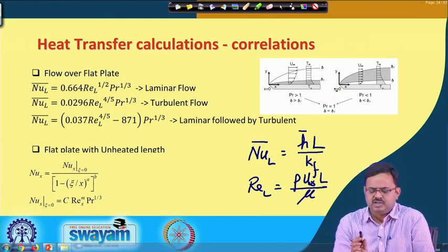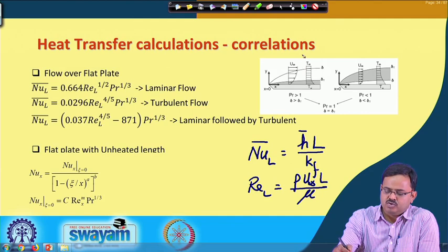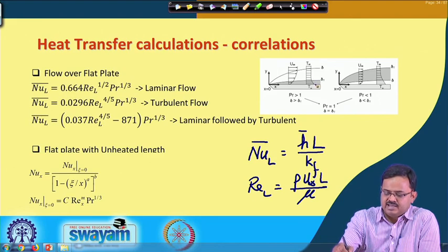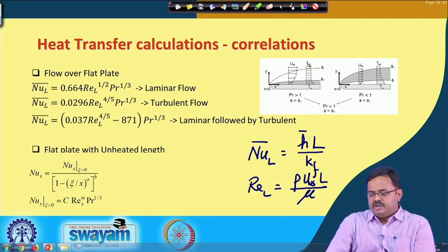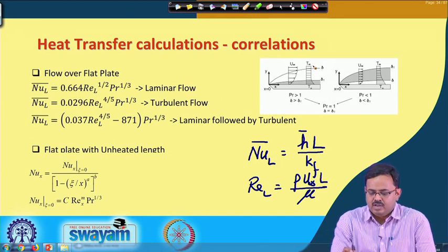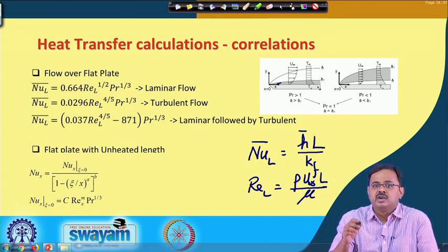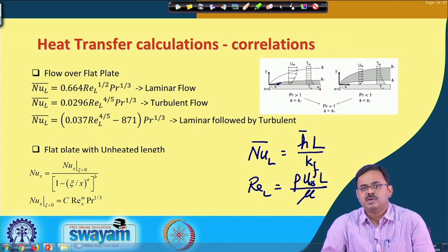So, this is flow over a flat plate. Forget all this. So, you have a fluid flowing over a flat plate, and as we know, velocity increases from 0 to the mean value as you move away from the plate. The temperature, if it is a heated plate, is highest at the plate and then reduces and slowly takes the value of the ambient at which the flow came in. If it is a hot plate, if you bring your hand very close, you feel the warmth. If you move away, you have really come onto this range and you do not feel the warmth anymore. So, this thickness within which the temperature reduces from the hot surface temperature to the ambient temperature is known as the thermal boundary layer.